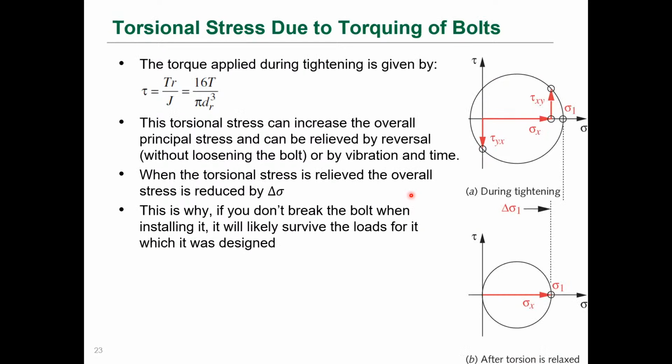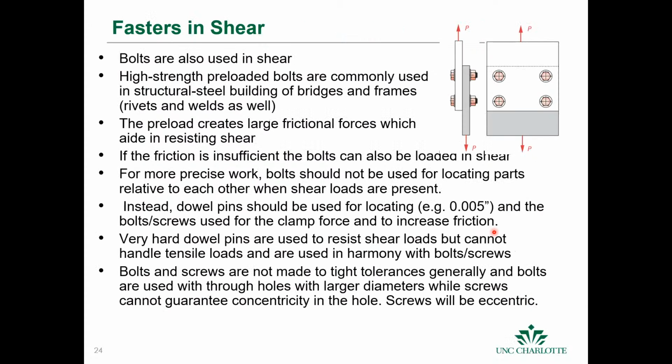I guess the point is, when you're installing the bolts, the torque is not going to be super accurate, off by like 10 or 15%, and if you just go from that, the stress is actually relieved. Okay, so that torque value that you measure is not going to be the same that it experiences because of this relaxation. Okay. All right.